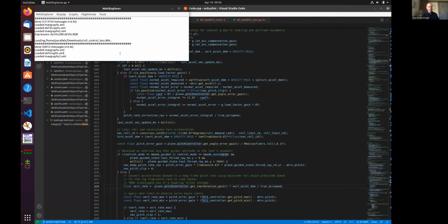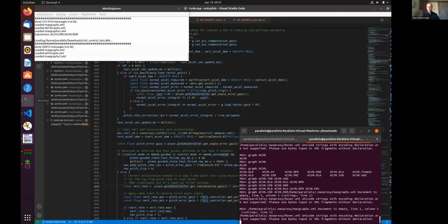But one of the problems I've run into with twin engine aircraft is that sometimes you can have propellers which are mismatched. You might get two propellers, a 13/7 or 13/8 pitch, and you'd think they're identical. But if you run them on the thrust stand, with some manufacturers the pitch across two propellers can differ by 5%. So that's a 5% thrust variation for the same RPM. And if you've got a twin engine aircraft, that can cause some real problems. So I was just going to show you what this looks like.